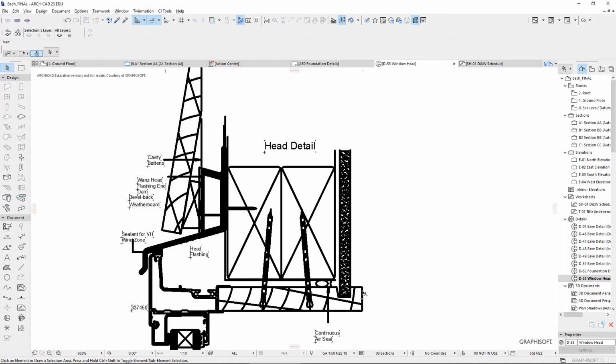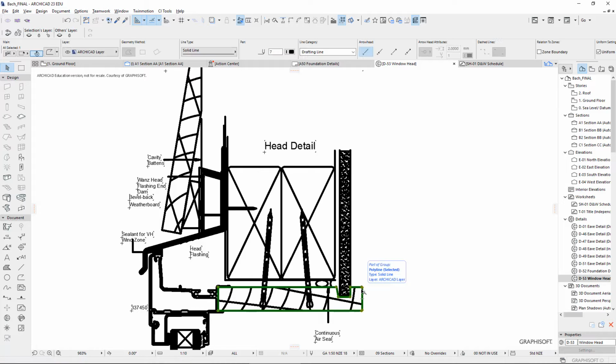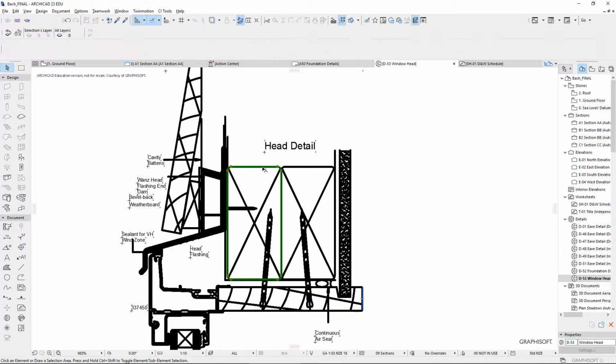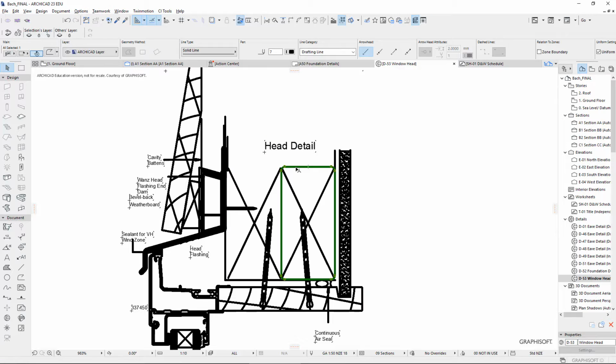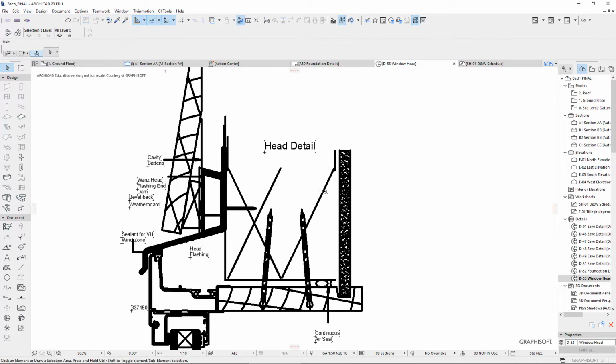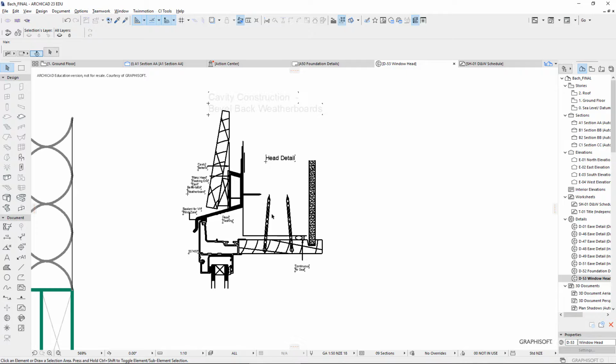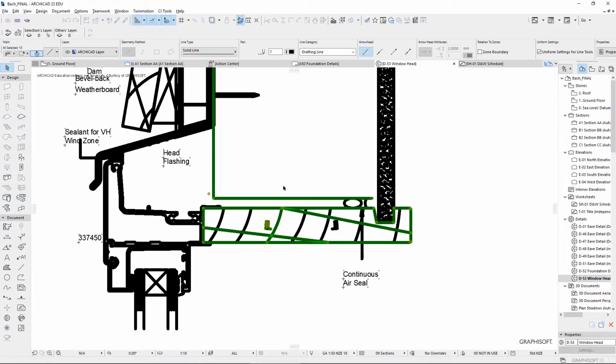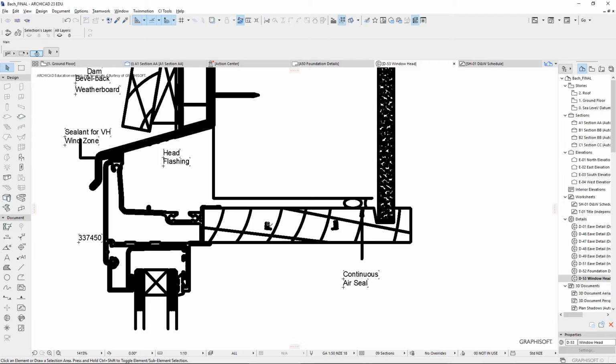So you're missing information here. You're missing whether this has got the right kind of jamb liner, whether it's got the right kind of timber here. Do we need to get rid of those and put some of my other timber in? The insulation's missing. Is your building wrap there? Is your air seal there? I often get rid of these things like the nails because I don't want to see the nails. You have to tell someone that they're going to put those in place. And I need to go back to that mode, I think.